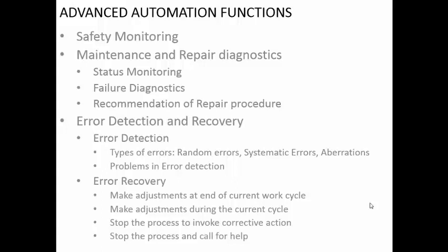Now, recommendations are only recommendations. The maintenance operator has to apply his mind to ensure that he is not blindly following. Sometimes the MCB switch has been tripped, but the moment you switch it back on, it trips again, and the solution is not continuously resetting the MCB switch.